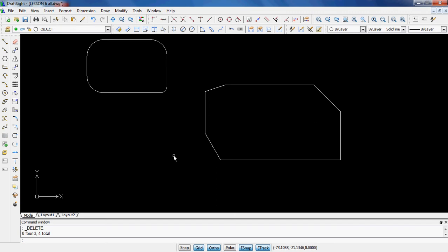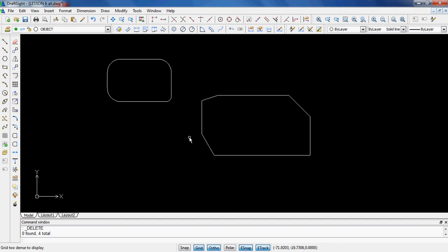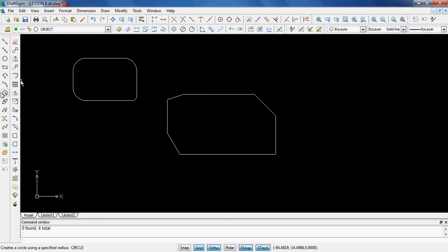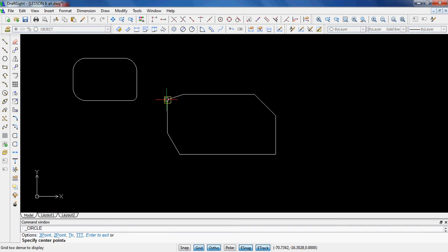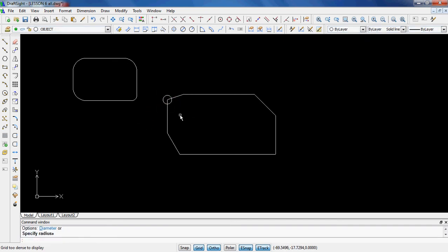I believe 7D goes into the move command, and this is kind of cool. I'm just going to draw a circle around here, draw a circle at this point right there. And what it wants you to do is to know how to move or make multiple copies of things. So I think in the past I've shown you, you can select the circle and hit Control C and Control V. The only problem with that is, and I can keep hitting Control V, it doesn't allow me to select it on a very good spot.